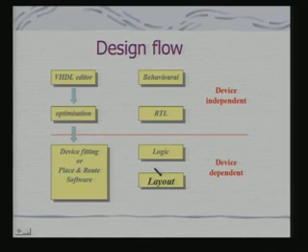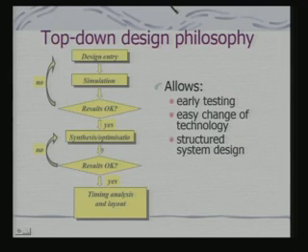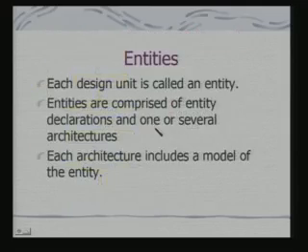And many of the designs of embedded systems are built around these kinds of soft cores. So, the design philosophy is you have a design entry, simulate, if it is okay, else modify, then you synthesize and optimize, again do the simulation, and then do timing analysis and layout for coming to the final form. So, early testing, easy change of technology and structured system design. Before even coming to the device level, at layout, we can do a simulation and testing of the system to know its correctness.